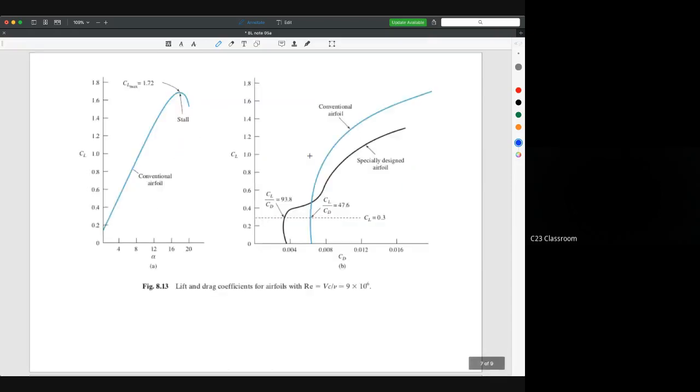So this is another example. The idea is the lift and the angle of attack. The bigger the angle of attack, the more you may increase the lift force, but at a certain point a stall happens. Stall means your airfoil may lose its lift force, so it maybe cannot continue to support your flight. Your flight will lose the ability to fly. So this is a very critical point. In aeronautic engineering, they are very alert about this.